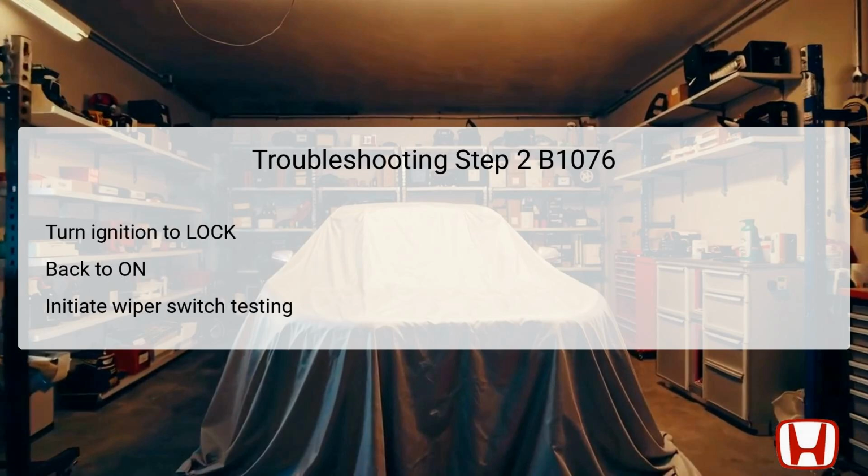After clearing DTCs with the HDS, the next step is to turn the ignition switch to the lock position and then return it to the on position. This cycle is vital as it refreshes the vehicle's electronic systems, allowing for a proper evaluation of the wiper system. Following this, the wiper switch should be turned to different speeds, intermittent, low, and high settings, holding each position for at least 6 seconds.